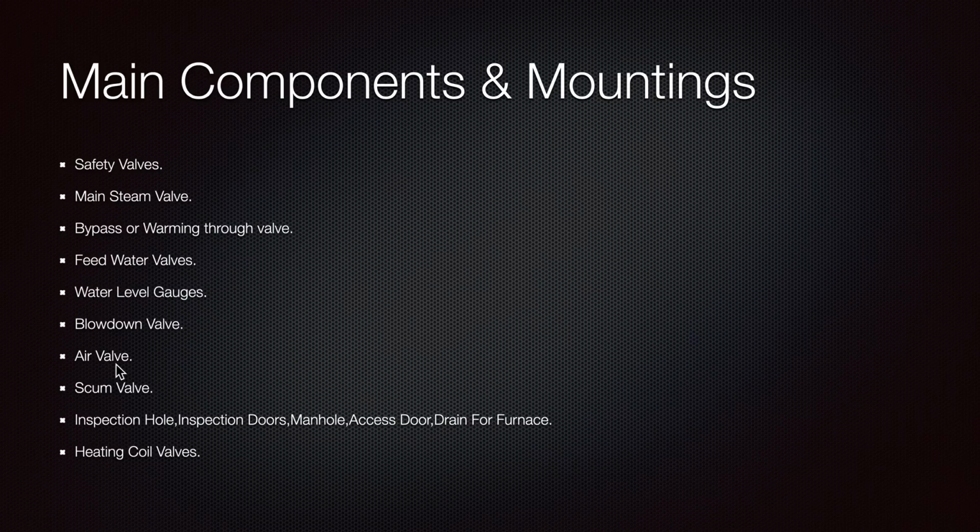and it's really important to keep it free, because when you are washing the furnace you do not want any water to remain there. So make sure that the drain is free before you wash your boiler, because afterwards it will be much more difficult to clean it. And how to prepare: put a hose inside, open the water and see if the drain is working.